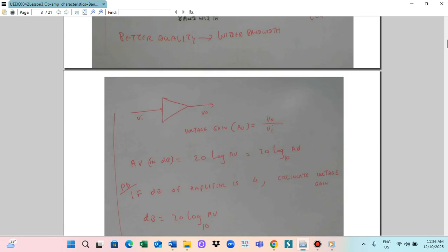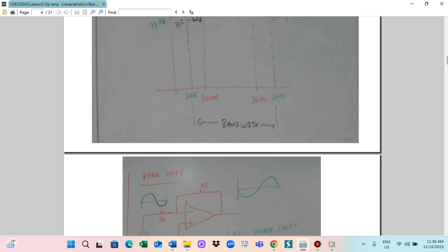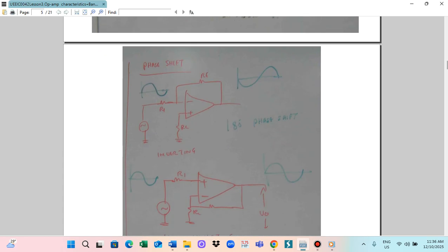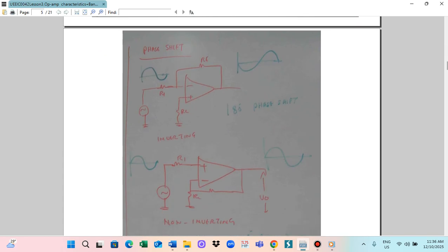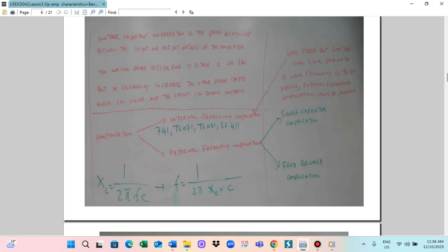This means that inside the operational amplifier, some of the transistors are not equal. So they are not the same, and it will cause the offset DC voltage. Because of this offset DC voltage, the voltage level will be changed.